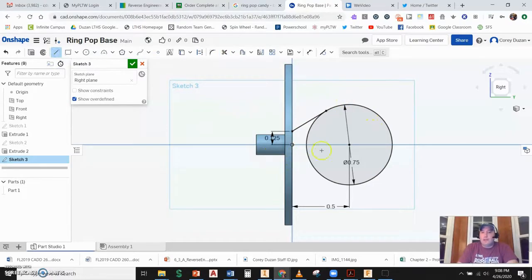All right, I'm now going to go ahead and draw a line. Start this from the center point, send this straight over, and now what I'm going to be doing is looking for mirror. Now this is the only thing that's different when it comes to OnShape. It's actually asking you to select the mirror line first and then the geometry that you want to flip over. Okay, no problem. We pick on the line that we just created for our mirror line. Now we can come out here, grab that line, and everything has just been brought over according to that mirror line. All right, so that worked pretty well.